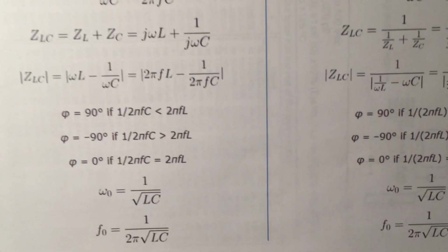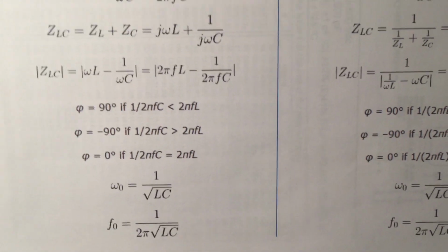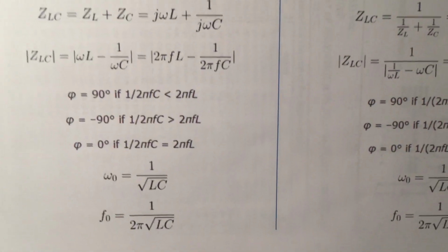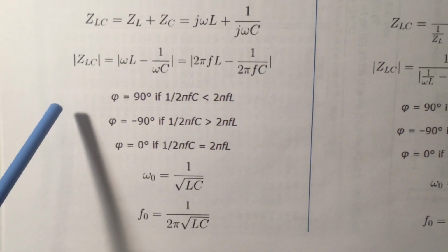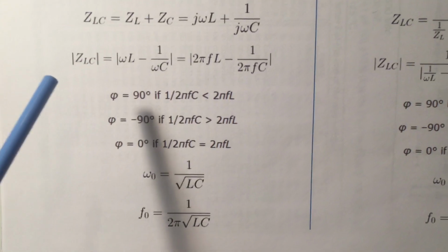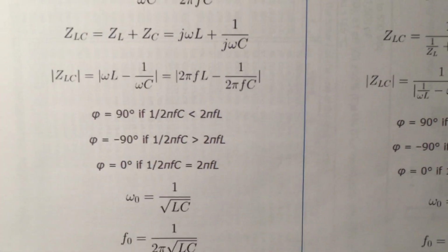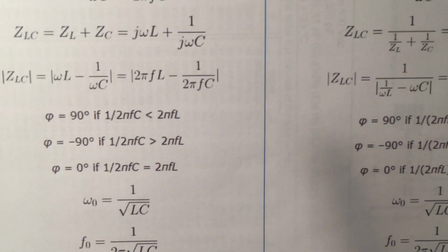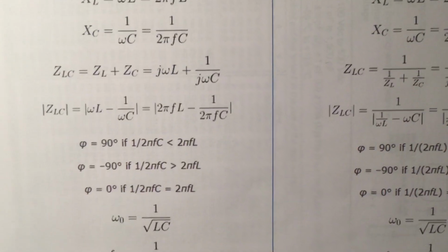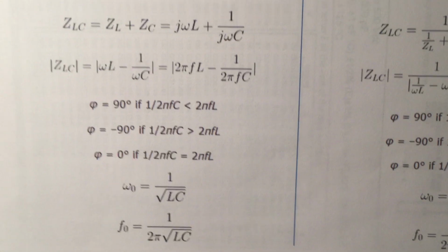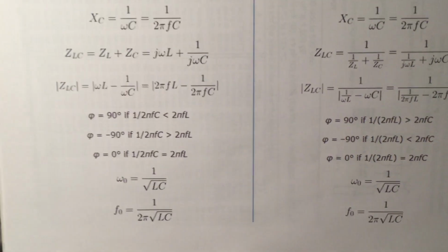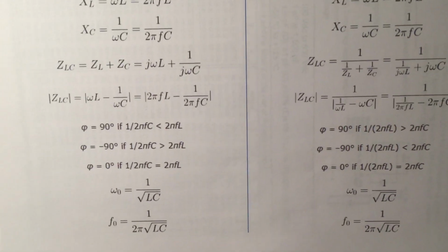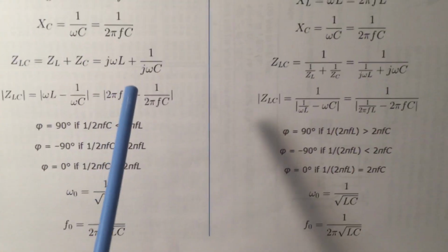So ELI is ELI. So the L in the middle is inductance. And what we basically have is impedance that's created from the phase shift between the voltage and the current. In an ideal capacitor and an ideal inductor, we have a 90-degree phase shift. But unfortunately, we don't live in an ideal world, so we have these parasitic effects that affect the actual performance of these components. And we're going to actually look at that on the vector network analyzer in just a few minutes.